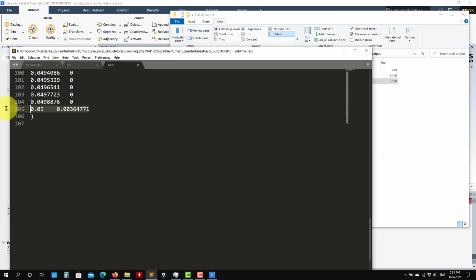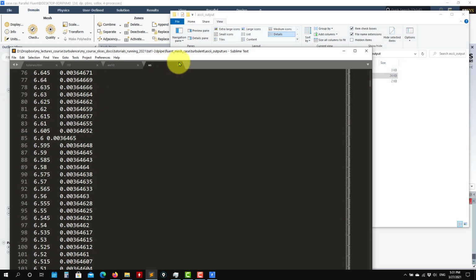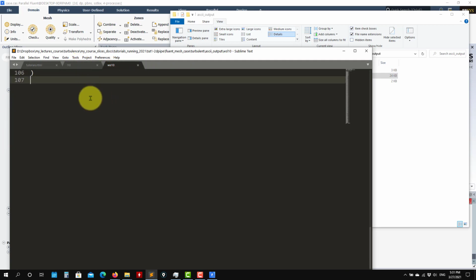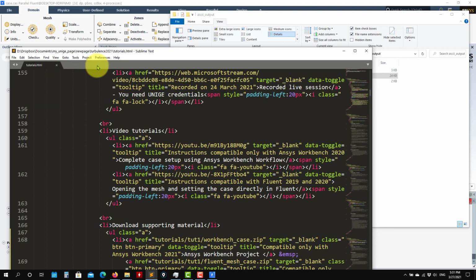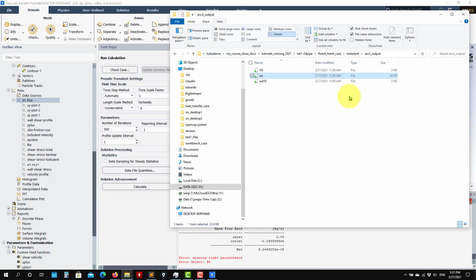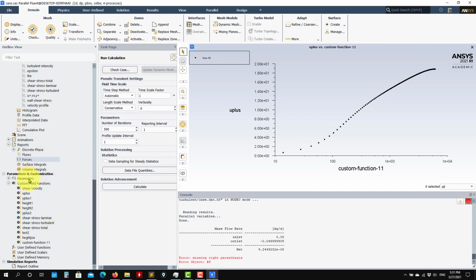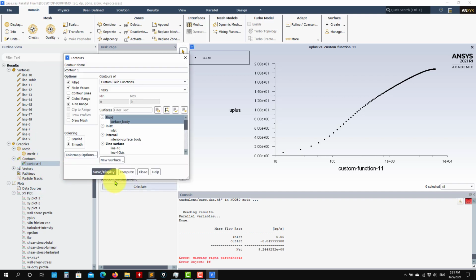So this one, WSL10, is the shear stress in the line normal. So just the last point. Or if you want along the wall, it is this one. So this is the only information that you need. Actually, you just need this. And this one, you will put it there to compute the shear velocity. And then using Python or MATLAB, you can do your plot. I prefer to do it externally, so in the 3D tutorial, we're going to do it, okay? So I'm going to save these files, and using Python, I'm going to show you that. So I think I have covered everything regarding this one.